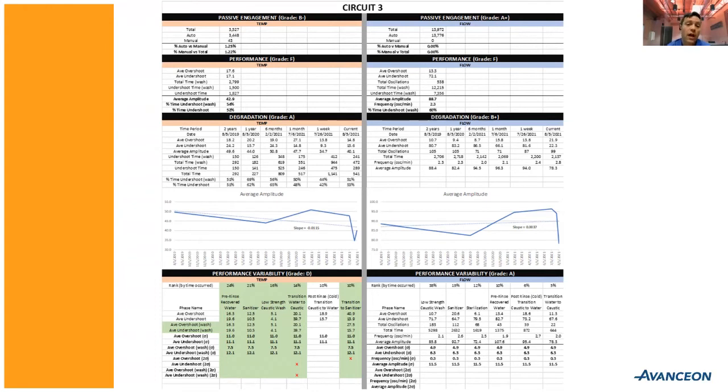And so at the end of the day, not only did this give them specific quantifiable detail to that general feeling of poor performance, but we were able to discover significant savings in both energy and runtime due to a number of issues. We saw issues with the PID implementation. There were both general and multimodal tuning parameter changes that needed to be made, as well as taking a look at the auto to manual transfer. And so we've been remediating those loops to realize the benefits.